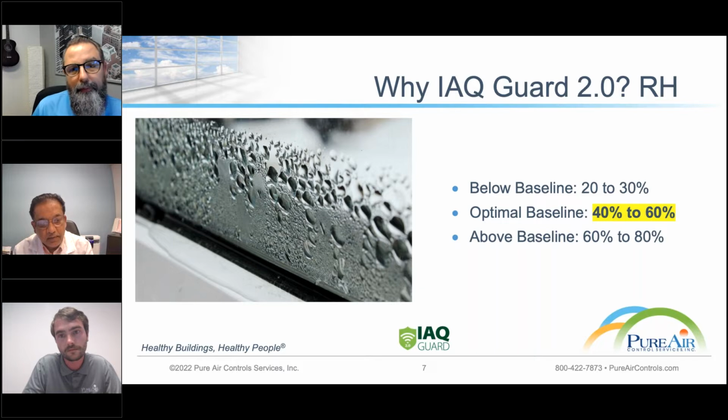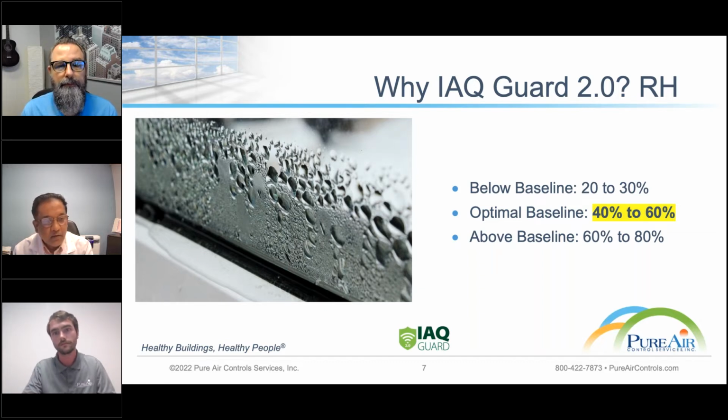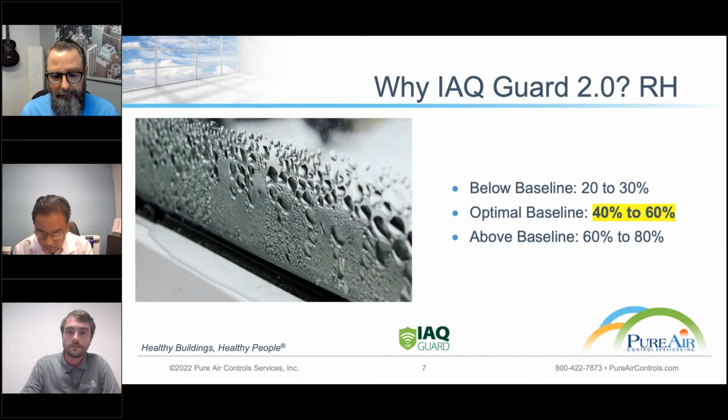So if you have a moisture content certainly above 60 to 80%, then you are more vulnerable than otherwise to get some mold growth going. So it is very important, and this kind of valuable data can be at your fingertips if you are utilizing these kinds of monitoring devices that can give you a very early indication of any incoming problem.